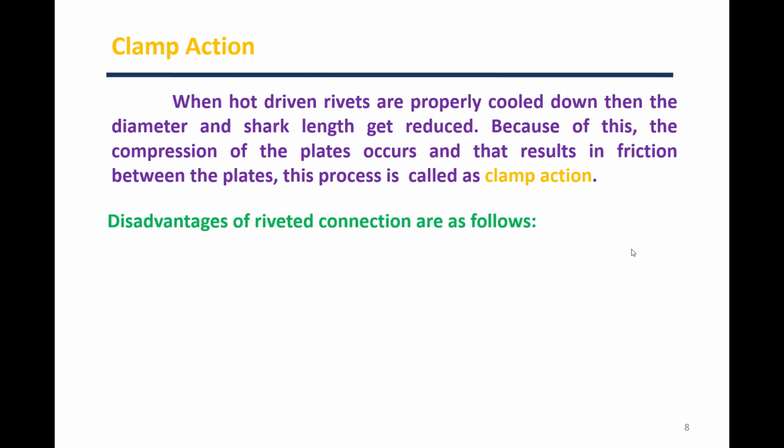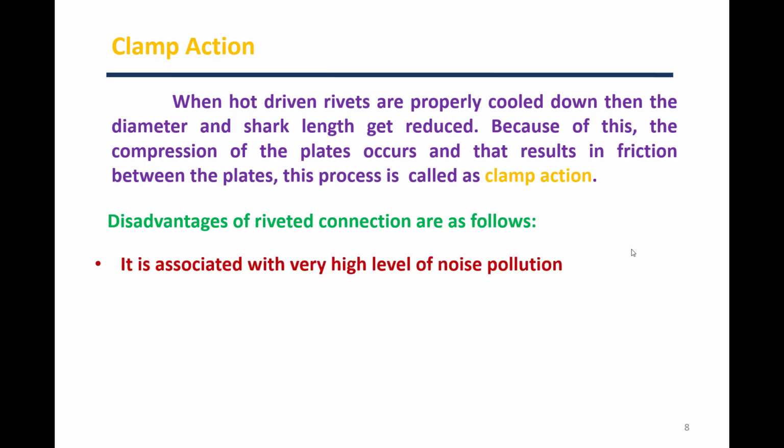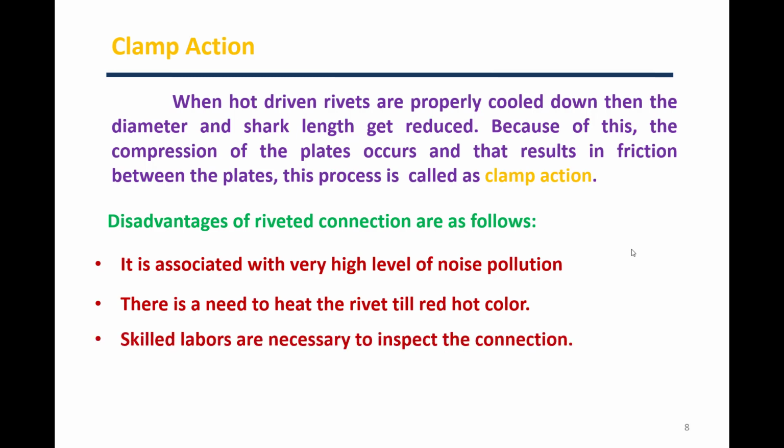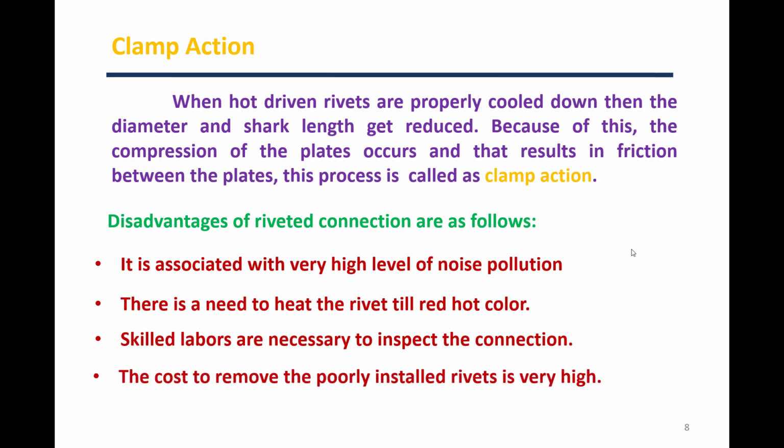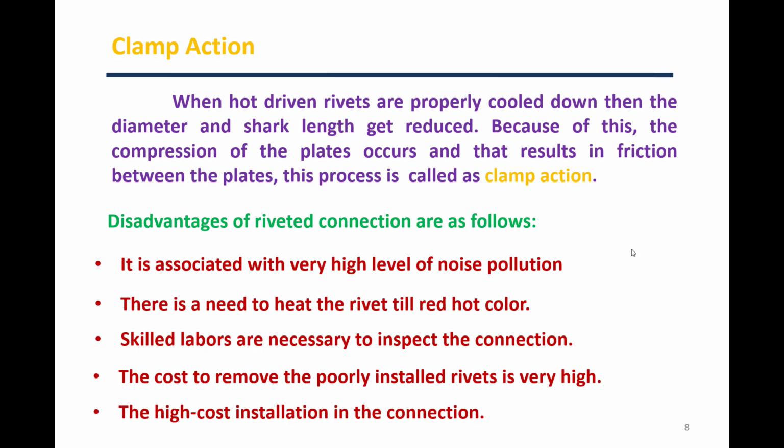The disadvantages of riveted connections are as follows. It is associated with a very high level of noise pollution. There is a need to heat the rivet till red hot color. Skilled laborers are necessary to inspect the connections. The cost to remove poorly installed rivets is very high. So there is a higher cost of installation in the connection.